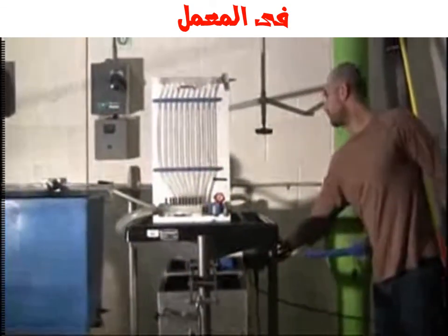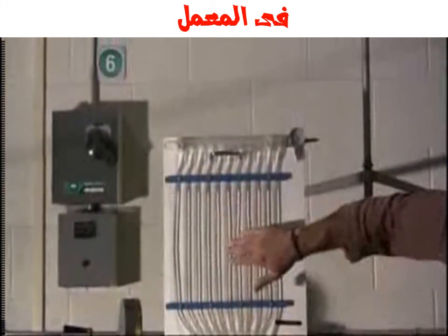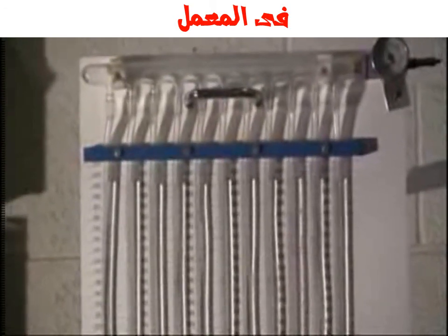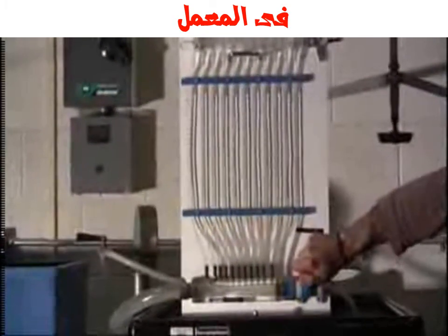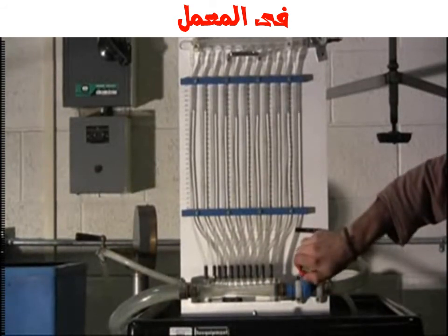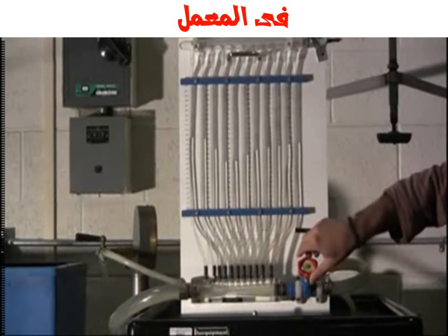Start the pump. Remove any air bubbles from the manometers by tapping gently on the manometer tubes. Make sure that all the manometer readings are high and approximately equal. If not, seek help from the lab technician. Check that the Venturi device is operational by increasing the flow and observe the pressure drop in the manometers. The pressure drop should look like the following.